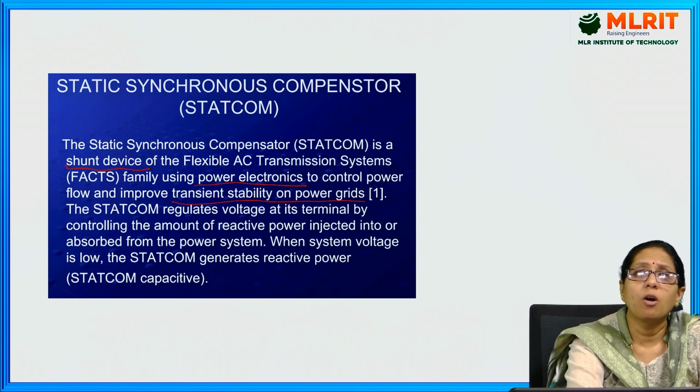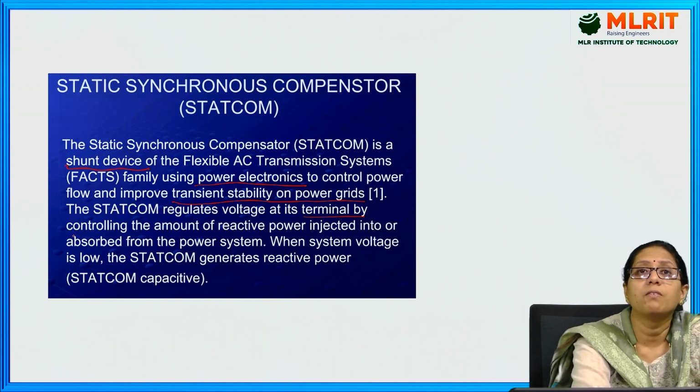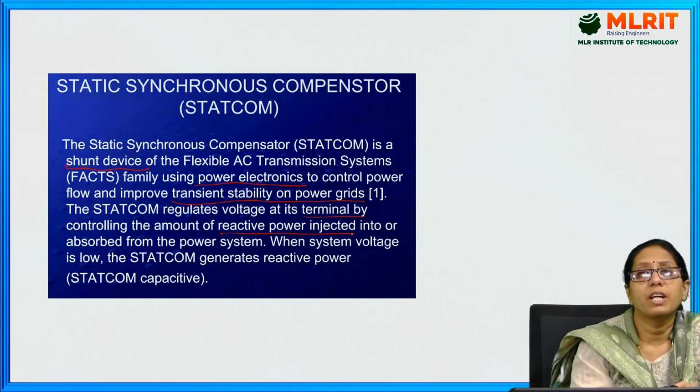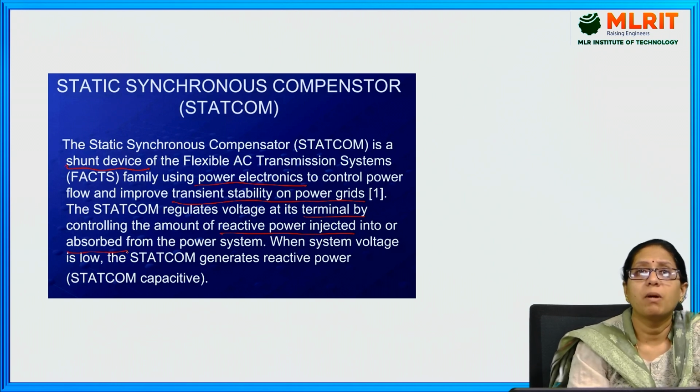The STATCOM regulates the voltage at its terminal. That means at the terminal we will be connecting the STATCOM, and it controls the amount of reactive power injected into or absorbed from the power system.